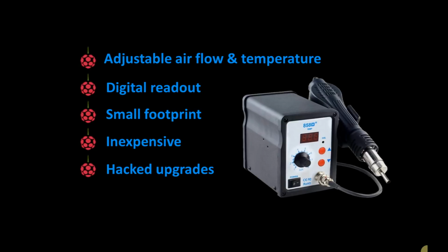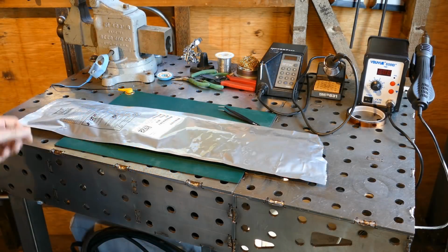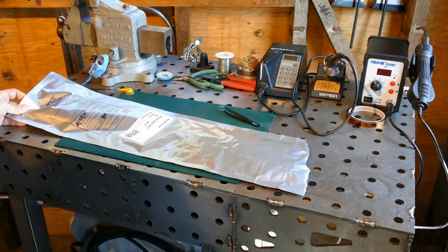The 858D is sold by many vendors, and it's hard to tell what you're going to get inside in terms of PCB, microcontroller, and components, but most of the shortcomings have been addressed by hackers. There are schematics, add-ons, adapter boards to swap out the MCU, and improved firmware is available. I also went ahead and ordered a replacement CP2104. It only cost $1 and change with shipping.